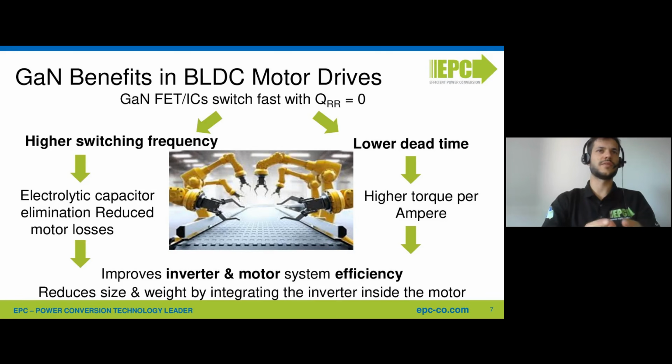So it's, let's say, a little more pure and makes the motor more efficient in terms of electrical to mechanical power. And the effect on the inverter is that thanks to the much lower ripple on the voltage, it's possible to reduce a lot the size of the input filter, reducing the cost of the bill of materials and the dimensions of the inverter, which sometimes are important.